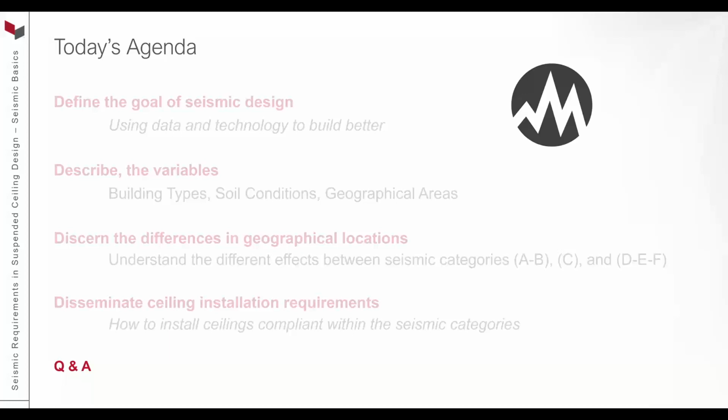But again, everybody is so used to cutting that grid and leaving that 1/8 inch that it's not typically any problem to any of the installers. And then the use of the ACM7 clip, that's what helps sustain or keep that cross T level during a seismic event, keep it up above. And also, that's why there's a perimeter wire required in category D. So it can be complicated, but for the most part, everybody is pretty used to cutting the cross T's that tight. We don't typically see many problems with that.